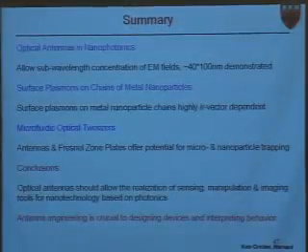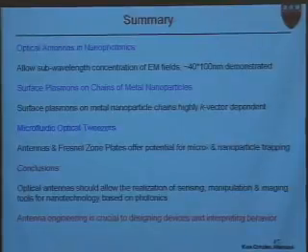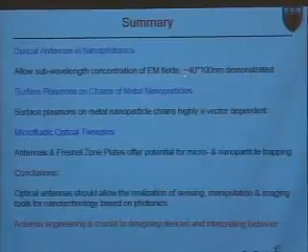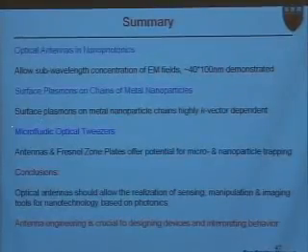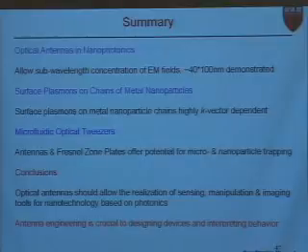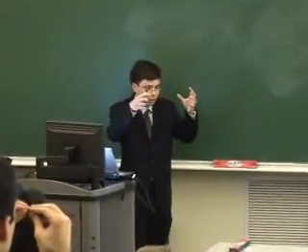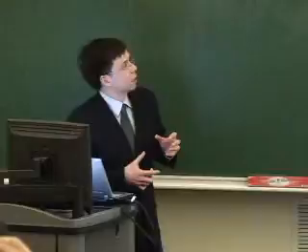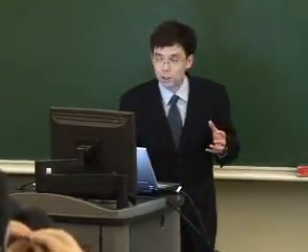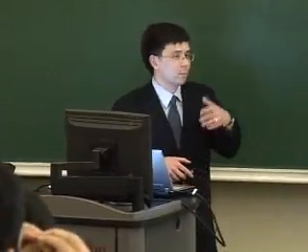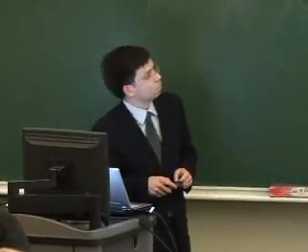So to summarize, we've seen that optical antennas in nanophotonics allow us to confine fields to tens of nanometers. 40 by 100 nanometers has been demonstrated. We've seen that for the surface plasmon excitations of these nanoparticles, one needs to carefully consider the neighboring nanoparticles as well as the environment, both the substrate and the medium above the substrate, to understand what the plasmon resonance frequencies are. And we've seen that they're highly k-vector dependent. That's important in applications where you're coupling from a waveguide.